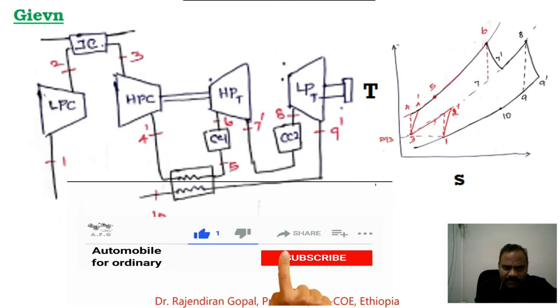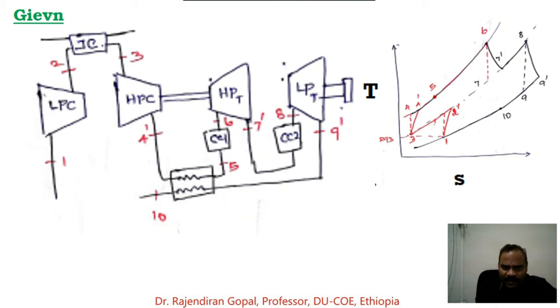Here, in the gas turbine plant, the air is compressed in two stages and expanded in two stages. The compressors are run by the high pressure turbine. The generator produces the power output from the low pressure turbine. Between the compressors there is an intercooler, and the air from the high pressure compressor is heated by a heat exchanger using the exhaust gases from the low pressure turbine.